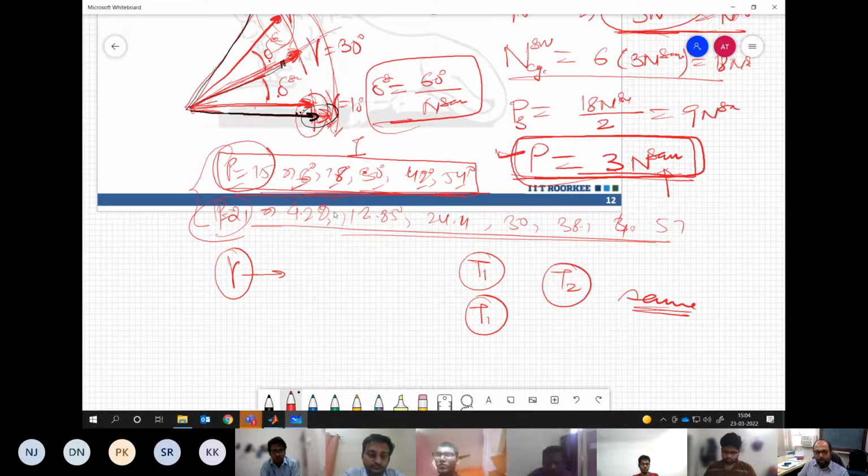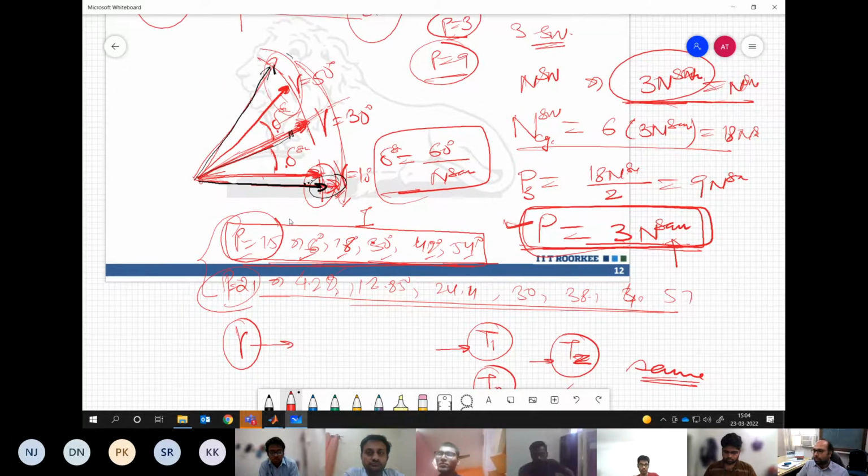Now the same thing is true for all the sectors 2, 3, 4, 5, 6. Which means I only need to compute these numbers once, TZ, T1 and T2. These numbers should be computed only once, and then we are repeating the vector sequence for every sector based on which vectors are forming the boundary of this sector. So that is what we will try to generalize today.